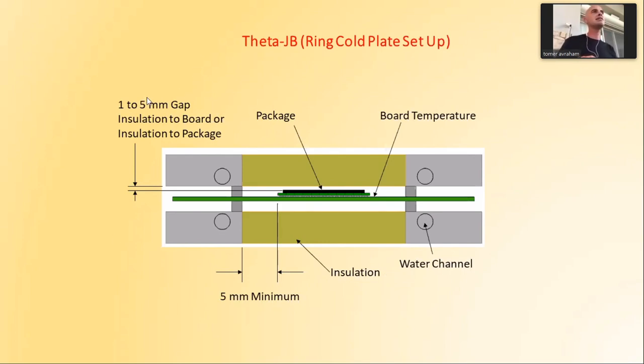There's a standard which explains exactly which power we use, which cooling we use, how much force is applied on the chip, what the installation means, and when and where we place the thermometer to check the temperature of the board, like 5 millimeters minimum, or exactly 1 millimeter, usually from the chip itself.